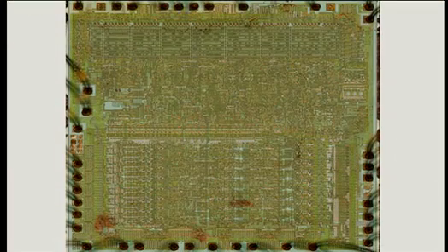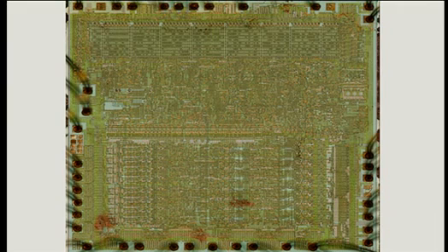After stitching everything together, at the end he had a 200 or so megapixel picture, and it turned out 6,000 by 6,000 would have been enough for reconstructing everything. He wrote a tool to draw the original polygons of the traces on top of the pictures that he took. This is the first picture, this is the second picture, and with his tool he drew the vias and drew the traces, and at the end you get all the traces on top of that. This would be the complete 6502 completely in vectors and redrawn. Of course, it needs some debugging.